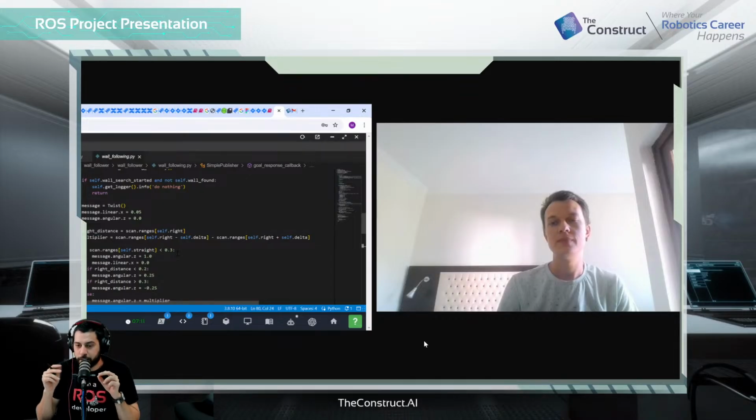Okay, and then two comments I saw. The first one is that I saw that in the wall following node, you do everything in the laser callback. And actually, I do not recommend that, because you did it correctly in the servers, right? You just got the message and that's it.